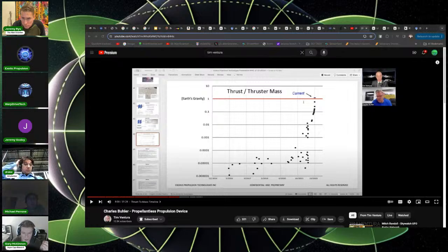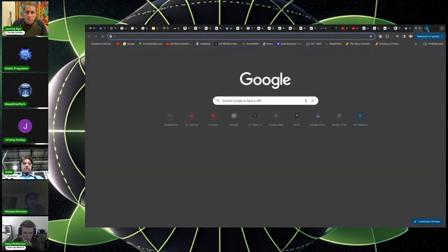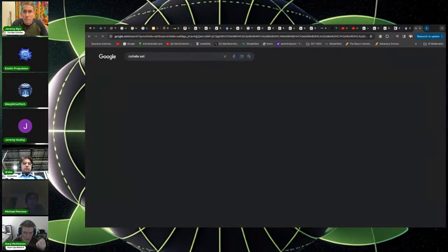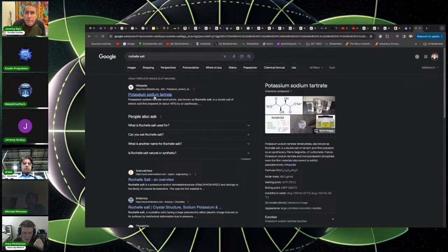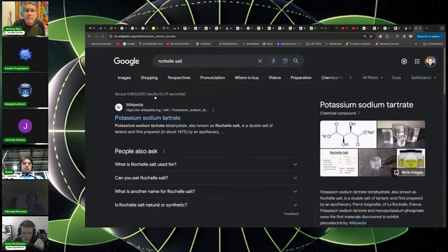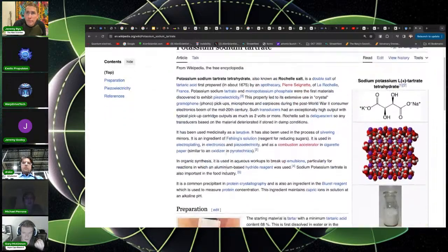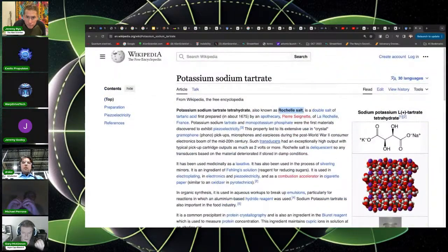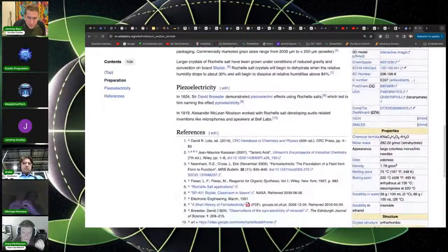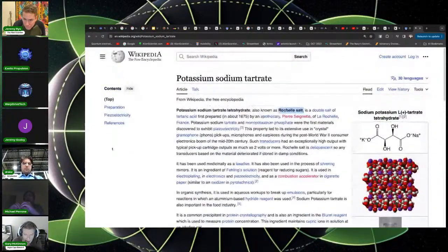So Gary, what I do is I take some Rochelle salt and I just use that as a binding agent for the calcium copper titanate. It works really well. I was using PVA. Yeah, you could, but the dielectric constant falls off so fast. If you have 2 things of high dielectric and then a small gap between them that's low dielectric, the final dielectric constant is not going to be that high. You want the dielectric constant all throughout to be very high, so you want your binding agent to be a high dielectric material.